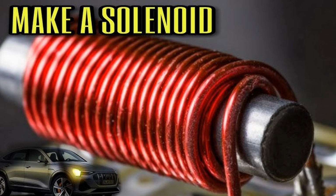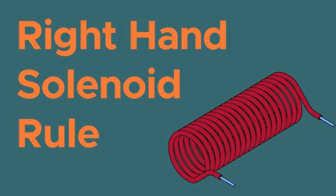8. Relays and switches. Electromechanical relays. Solenoids act as switches in electrical circuits, where a small electrical signal can control a larger power circuit. Circuit breakers. In power distribution systems, solenoids are used to automatically break the circuit when a fault is detected, protecting electrical systems from overloads or short circuits.